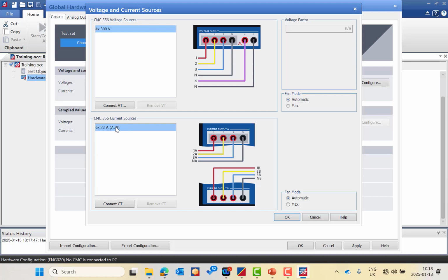And here also you have to identify how many channels of current you need. If you choose the 6 channel mode, the current output A will inject 3 phases, and the current output B will inject the other 3 phases. If you are online, it will give you some possibilities here to make parallel connection for the 3 phase mode and the single phase mode. If you are choosing the 3 phase mode up to 64 amp, you have to do the parallel wiring between the red and red for current output A, and same for Y and B and the neutral. So in the end, you will have 3 channels of current using the jumper ring, the current output A and B, so you can inject up to 64 amp.